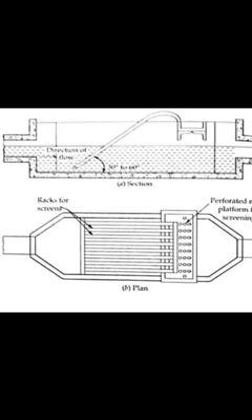So the medium screen, these types of screens have openings: the first is 5 to 10 centimeters, the second is 2 to 5 centimeters. So the screen size opening will be reduced. These will be mechanically raked units, used before all the pumps or the treatment units, such as before the stabilization ponds.